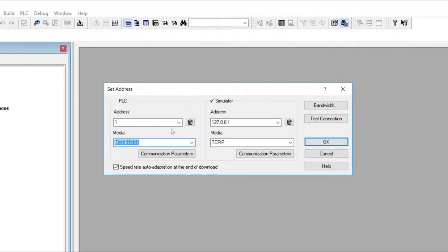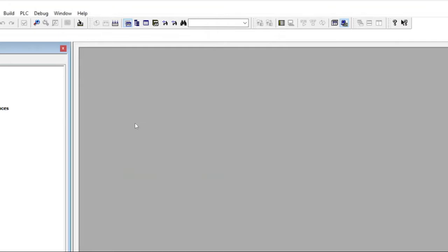If you are choosing serial or any of these serial connections at the top, you then need to set up addressing, which is the second part that you always need to set up when doing your communication interface. Serial interfaces work in node numbers, so you need to select the node number at which your PLC is connected.